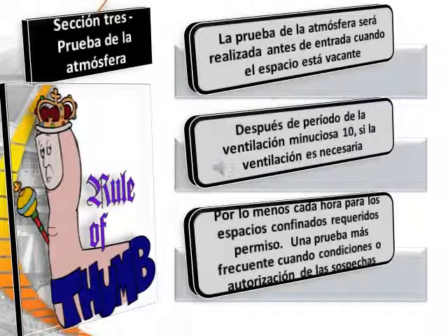Atmospheric testing shall be performed prior to entry when the space is vacant, after a 10-minute ventilation period if ventilation is necessary, and at least hourly for permit-required confined spaces. More frequent testing when conditions or suspicions warrant.